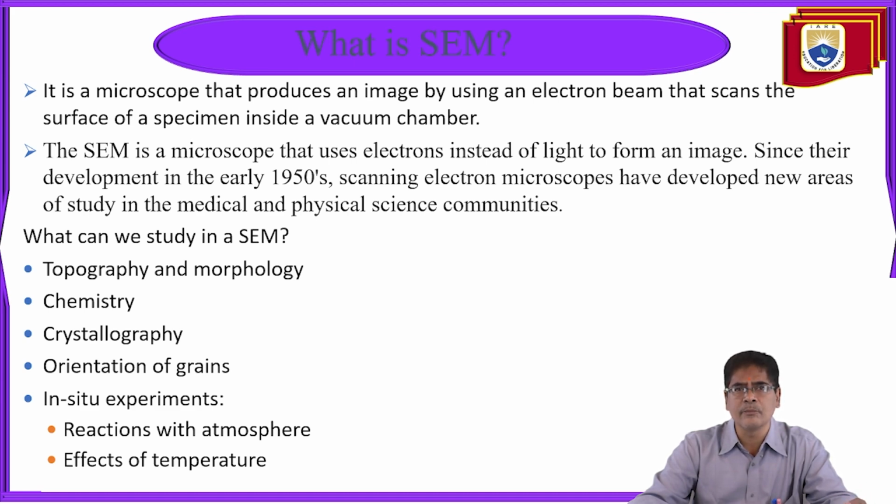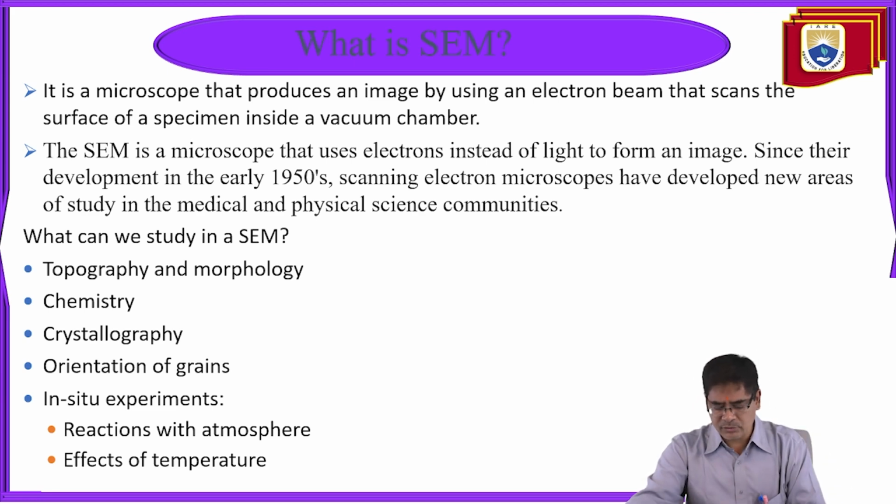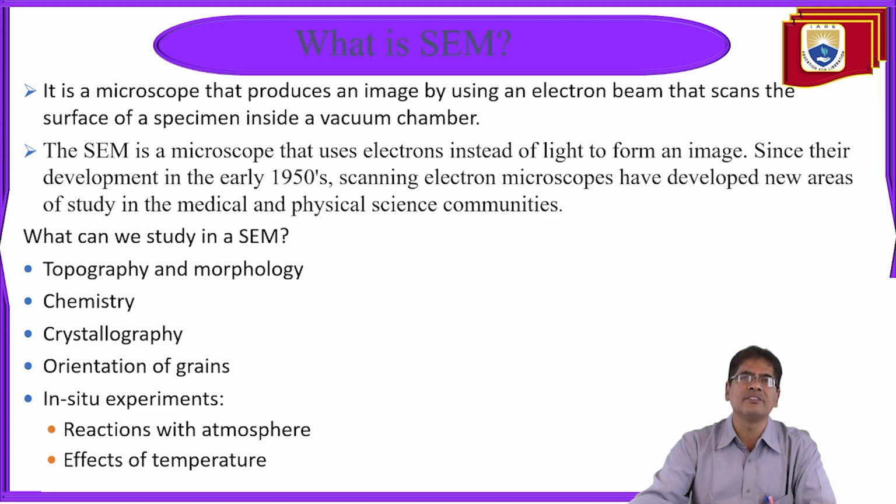So what is the type of crystal, and what is the orientation of grains, how the grains are oriented in different directions. In situ experiments, reactions with atmosphere and effects of temperature. So these are the certain parameters that we can study in SEM.